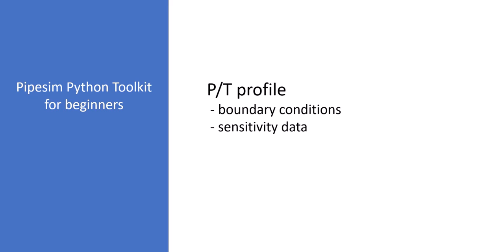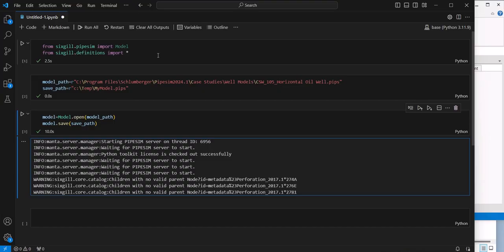In the previous video, I explained how to run PT profile simulation with different output parameters and report simulation results. In this video, I am focusing on boundary conditions and task configuration. I also will explain how to work with sensitivity variables. As usual, I use a case study model to show you an example. And in this video, I use the CSV 105 horizontal oil well model.